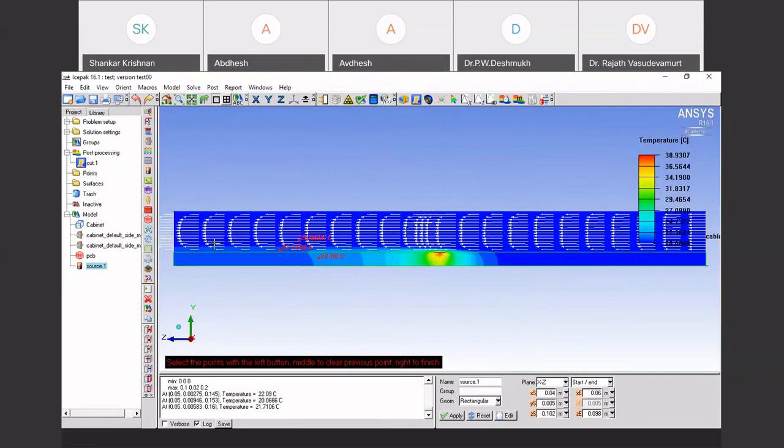If this is the airflow direction, you put a heat source, then you measure the temperature of the heat source by not applying any power to it. That adiabatic temperature, you use to calculate a heat transfer coefficient for the heat source, and the inlet temperature and static temperature for the first heat source is the same.